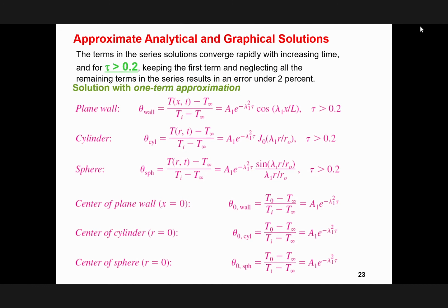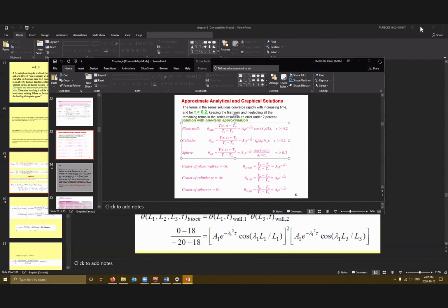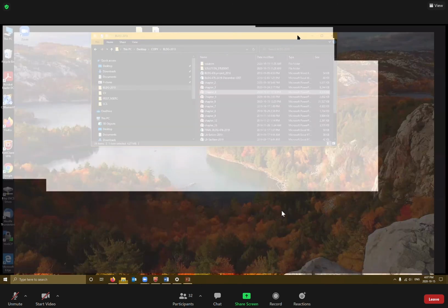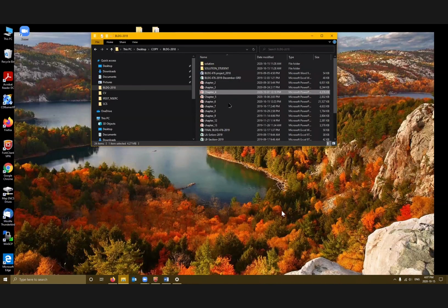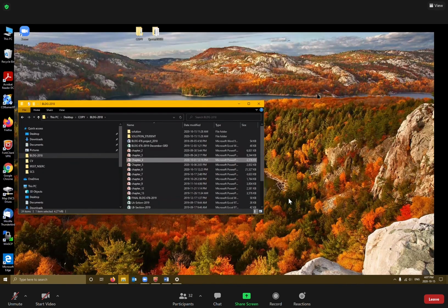Excuse me, sir. I have a question regarding my project. Yes, sir. So I got the feedback from the marker, and he said that my indoor temperature is too similar to the outdoor temperature. Do you know where I could have made a mistake for that to happen? Of course you can make a mistake, because the only time the indoor temperature is exactly the same as the outdoor temperature is when you have no person inside the building. And then you have infiltration. Probably you did not include the energy generated by the people inside the building.